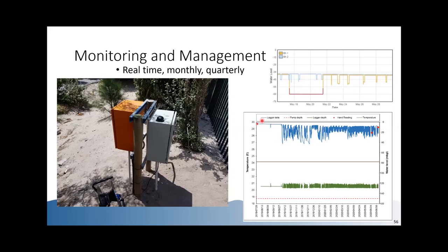And what you can see here is the water levels fairly stable. And when the borehole switches on, the water level draws down. And when the pump switches off, we see its recovery. Here's a period of longer abstraction. We can see the drawdown during that period, and we can see the recovery. So that's the water level data we're looking at.